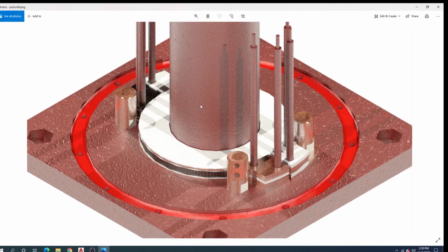Okay, and this tube right here is called the core tube. This is the core tube of the entire transformer. This too is a G9 phenolic material. As you can see, this is what keeps all the layers centered. And these terminal guides keep them from moving that way or that way.